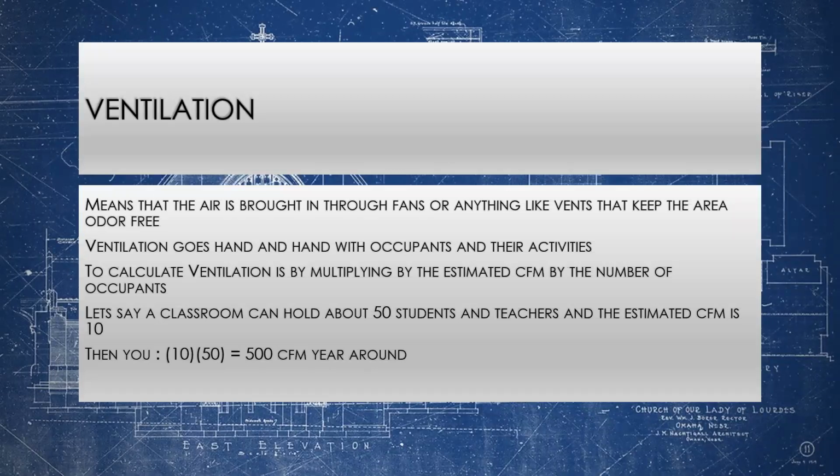Ventilation means the air that's brought in through fans or vents or anything like that, which also keeps the area odor free. Usually ventilation goes hand in hand with occupants and their activities. To calculate ventilation, you simply multiply the estimated CFM by the number of occupants.